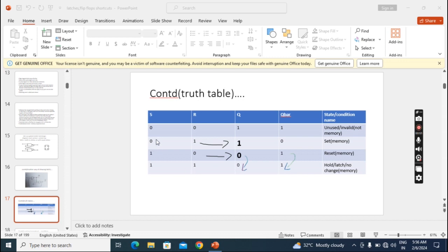So in that case we have to apply any of the other three combinations, either 0 0, 0 1 or 1 0. We can apply any of these combinations, because even though we don't know the second input and there is no output to feed back, in these three combinations at least one of the inputs is 0, and in a NAND gate if one of the inputs is 0, the output will become 1. Like that we can get the output.